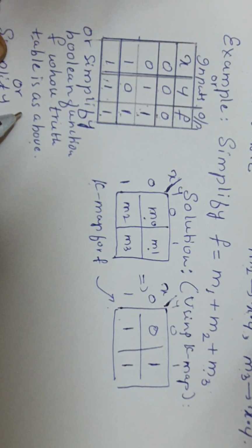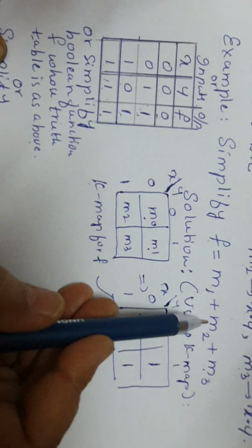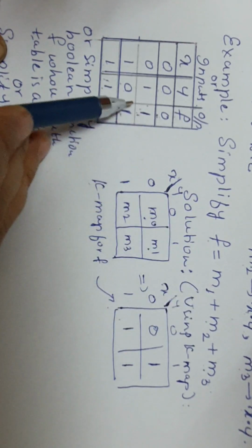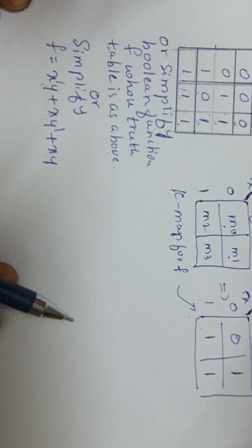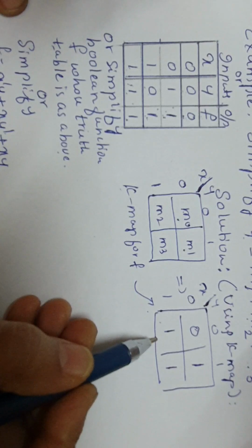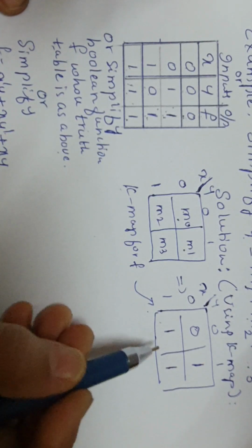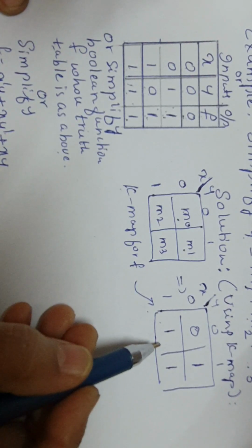The first thing is, whatever be the form of asking, expression, boolean function or truth table, we'll have to identify in the given function which minterms are there. For that, we fill the value 1 for those present, and 0 for those not there. So one step is over. For the given boolean function, we have filled the k-map.